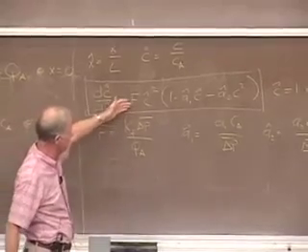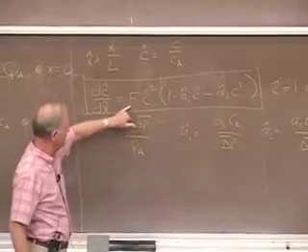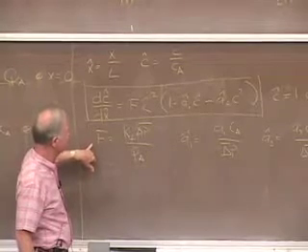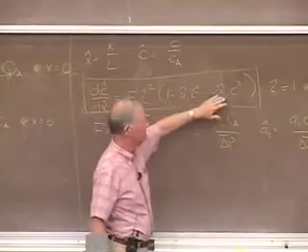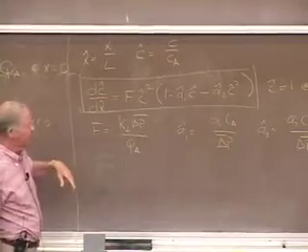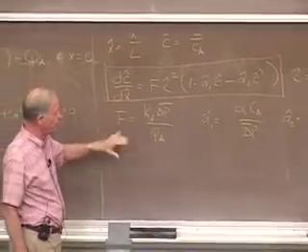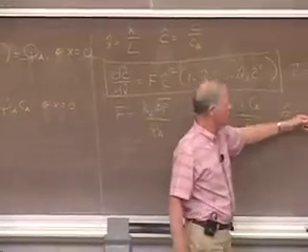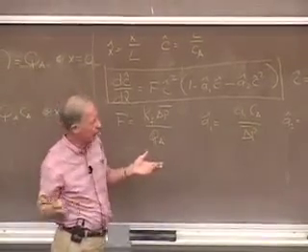It has a parameter in it, F, which is kf delta P bar over Qa. What must be the dimensions of F? What are the dimensions of these things? They're all dimensionless, so F must be what? This has no dimensions. So by non-dimensionalizing the equation, I've come up with one parameter, it's parameter F. And these other parameters, and these come from the quadratic, A1 and A2. Delta P bar is the constant pressure difference.